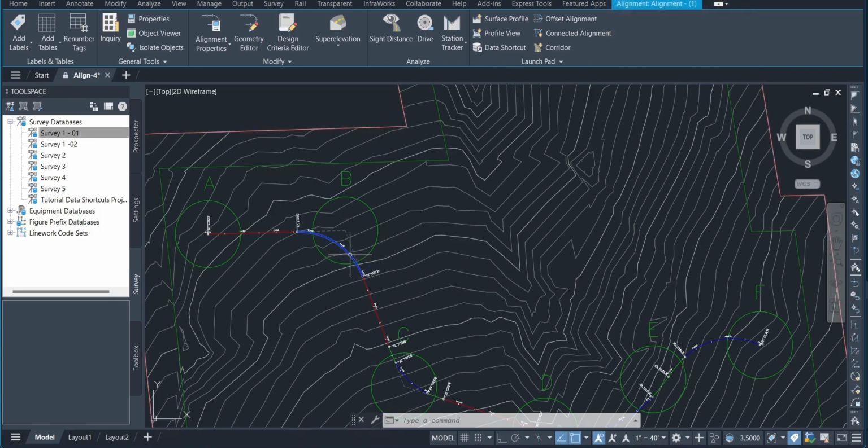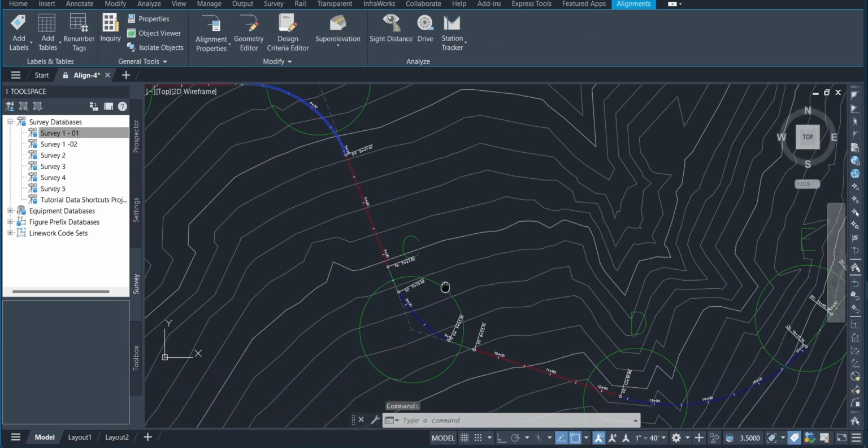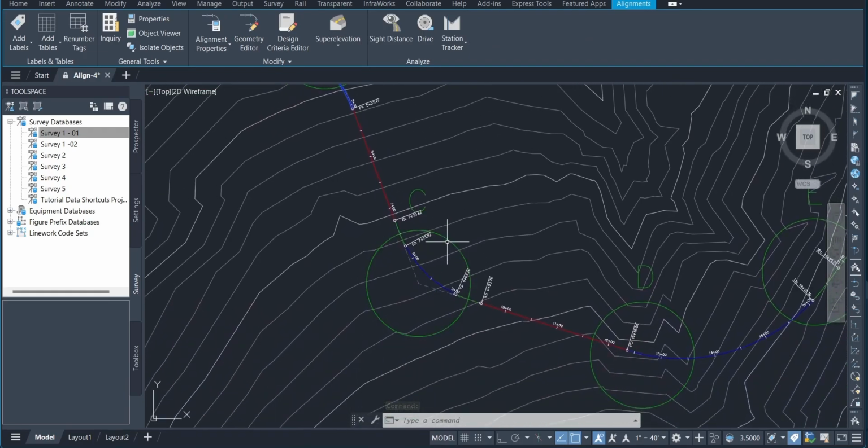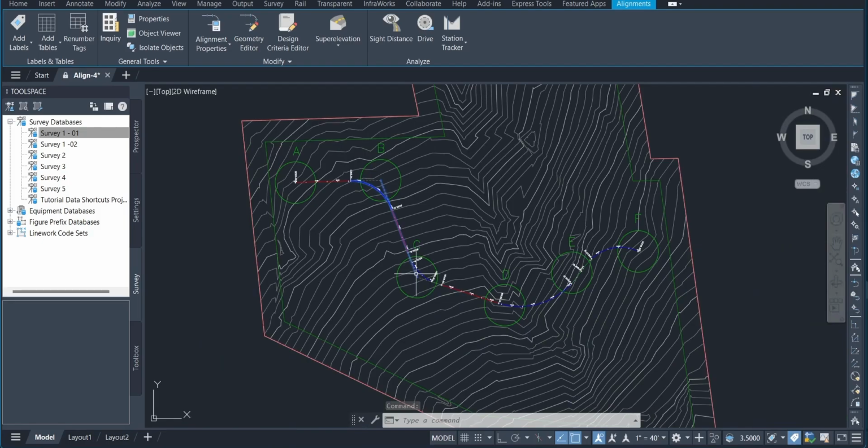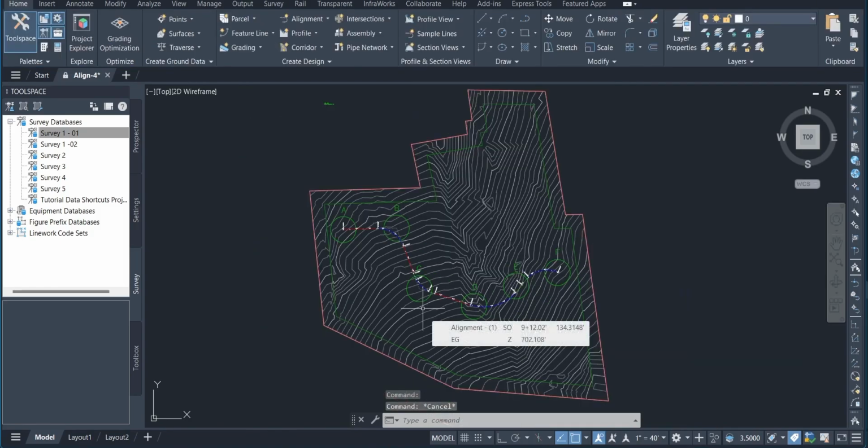In the drawing, Ctrl+click the spiral curve spiral entity in Circle C. Notice that the Alignment Entities Vista now displays the attributes for each of the entities you selected, plus the tangent between them. To display the parameters of another entity in the Alignment Layout Parameters dialog box, click the appropriate row in the Alignment Entities Vista. Press ESC to display all alignment entities on the Alignment Entities Vista. Exercise 2, Grip Editing and Alignment.